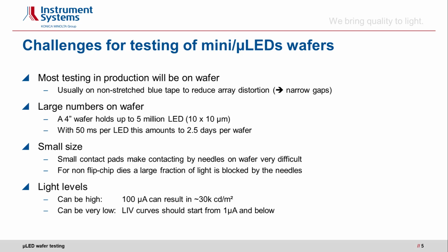Then we have simply huge numbers of dies on the wafer. A fairly small 4-inch wafer can already hold up to 5 million LEDs. And if we assume a 50 millisecond test time for each LED, this will amount to 2.5 days testing time just for one wafer. And this is simply too long and not acceptable to the industry.